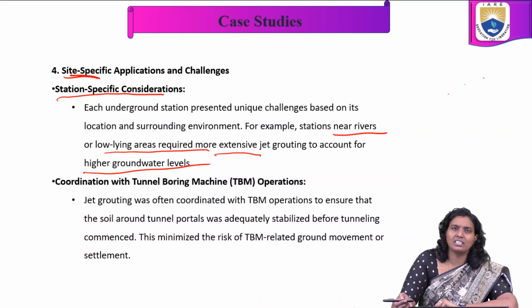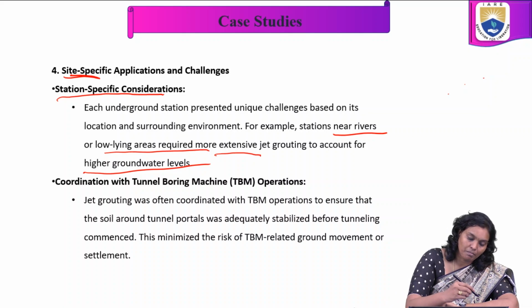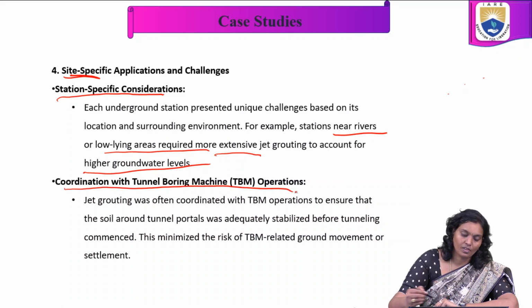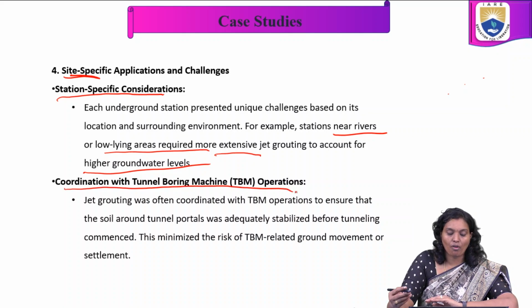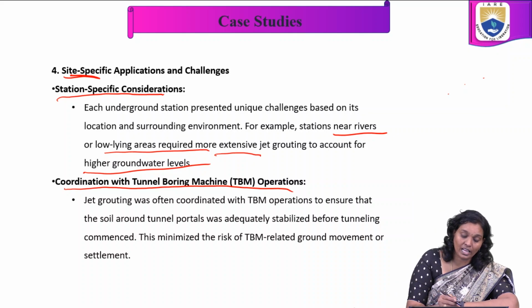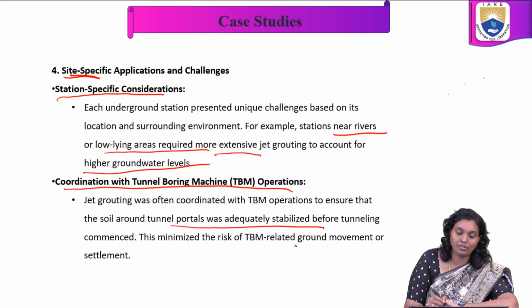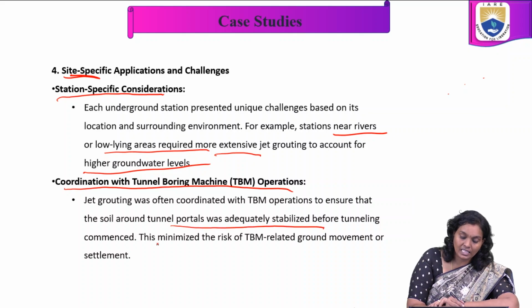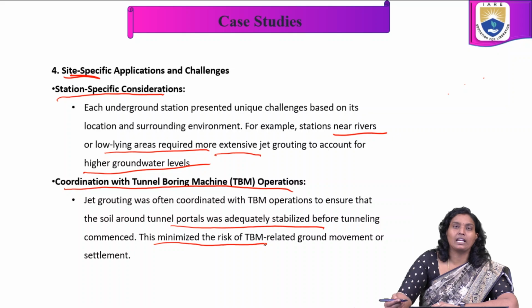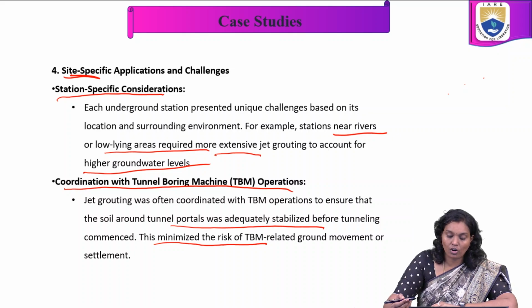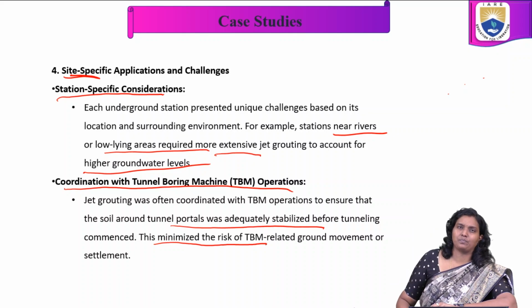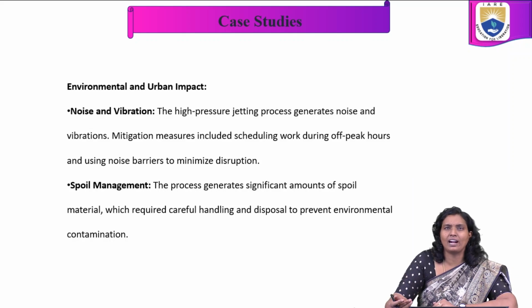Coordination with the tunnel boring machine operations: jet grouting was often coordinated with the tunnel boring machine operations to ensure that the soil around tunnel portals was adequately stabilized before tunneling commenced. This minimized the risk of tunnel boring machine related ground movement or settlement. These are the background things which we understand.